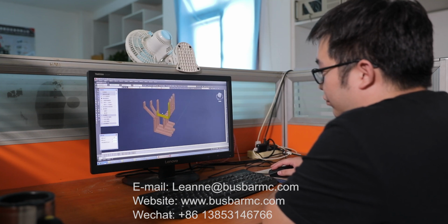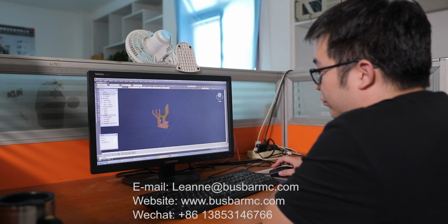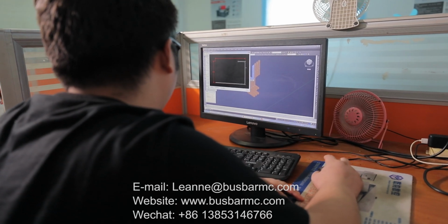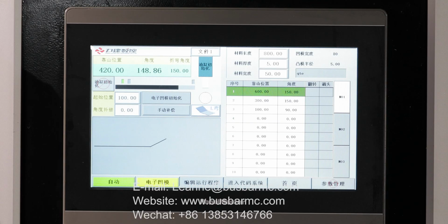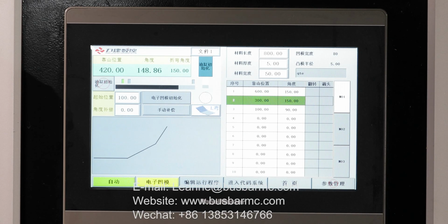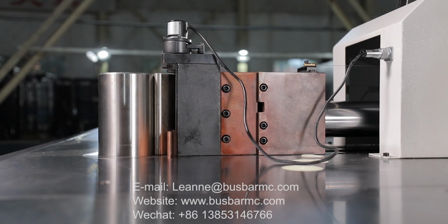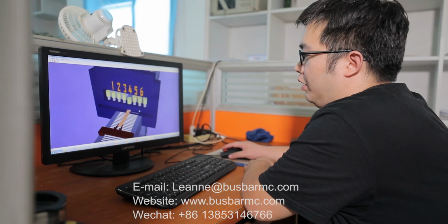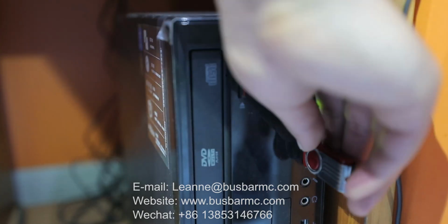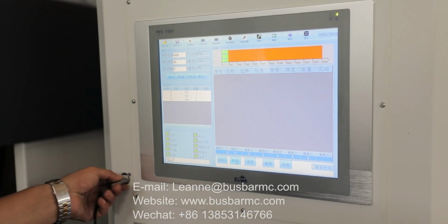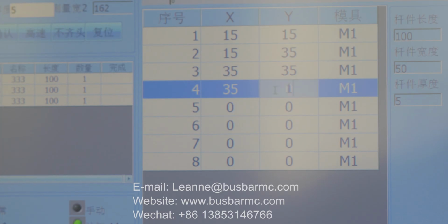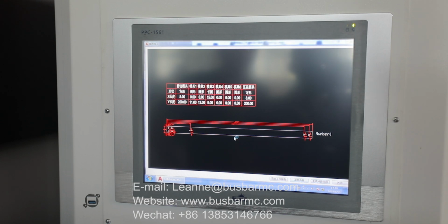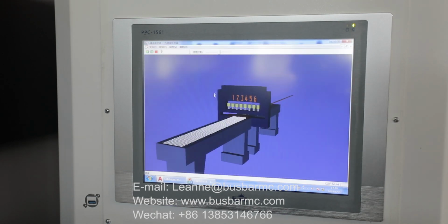The design system is simple in operation, and can directly realize three-dimensional bending, punching, and shearing bus bar pattern production, and can automatically find the bending sequence for a workpiece with many bends and realize programming automation. The auxiliary design system can be used to connect the bending machine with the MX602 CNC bus bar punching and shearing machine, which can accurately calculate the length after the bend is expanded and save bus bar costs when punching.